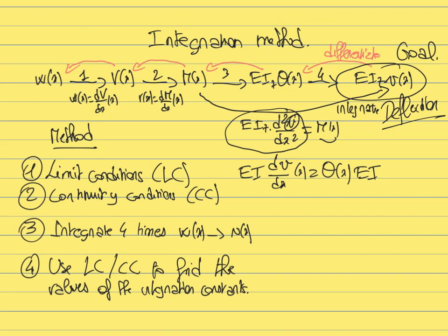And for this, again, the things that will matter are, first, the external load, external distributed load, external shear, and external moment that are applied to the beam, because this is what will dictate the value of the internal shear and internal moment. You also need some information about the geometry of the beam to get the moment of inertia, and you need to know the material that the beam is made of to get the stiffness, its Young's modulus. All those 3 things, geometry, stiffness, and external loads, will have an influence on the value of the deflection of the beam.